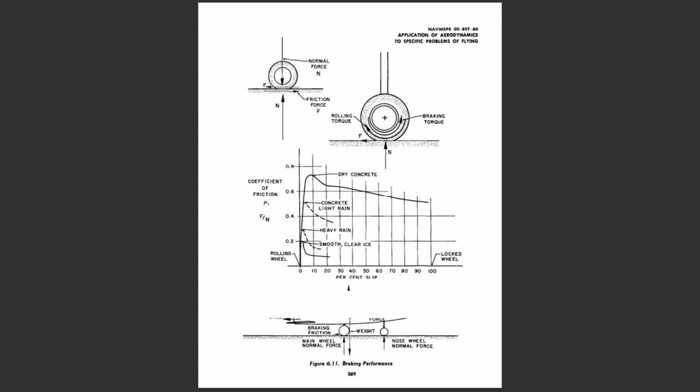If high traction on dry surfaces were the only consideration in the design of tires, the result would be a soft rubber tire of extreme width to create a large footprint and reduce surface shearing stresses, e.g., driving tires on a drag racer. However, such a tire has many other characteristics which are undesirable, such as high rolling friction, large size, poor side force characteristics, etc.